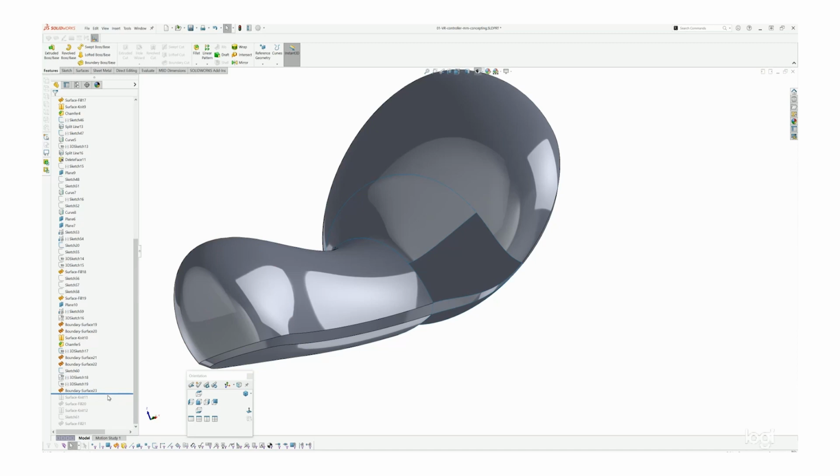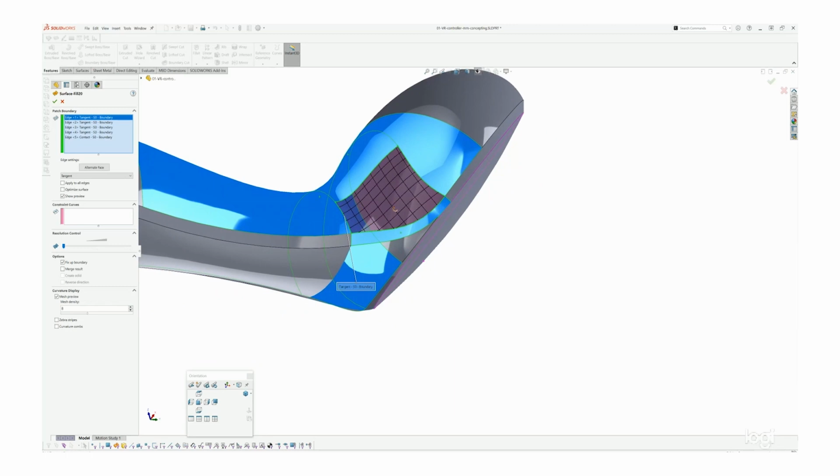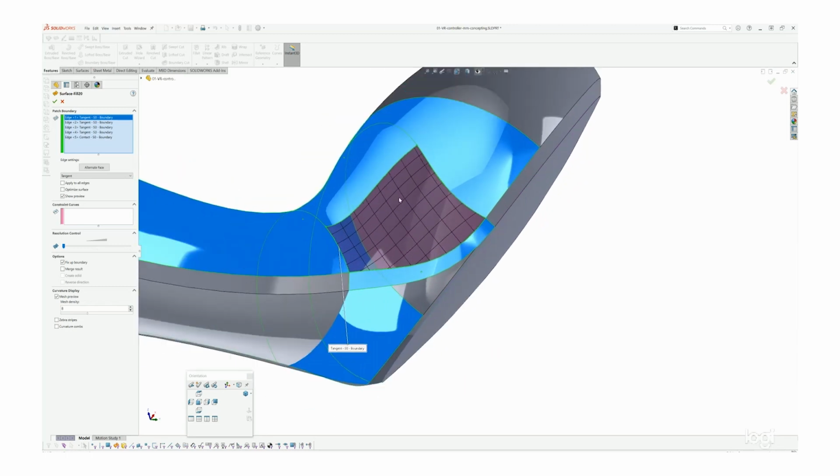And then all I have left to do is to finish this one feature over here. I created that as a fill instead of a boundary, even though it's four-sided, because I find that fill does slightly better magnitude tangency than boundary does. The developer explained it to me one time that if boundary creates a tangent reference, it's at 1, and a fill creates a slightly better tangency.